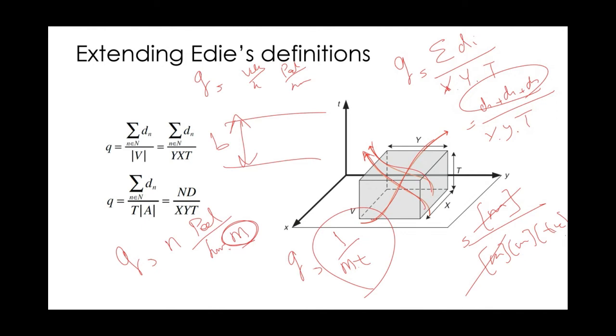So the wider the corridor that pedestrians are moving in, the larger the total flow would be, right? It's very similar to the number of lanes. Remember, in vehicular traffic measurement, we could say flow can be calculated as vehicles per hour per lane, depending on how many lanes it has. But because in pedestrian traffic we don't really have lanes, instead of the number of lanes, we have the width of the corridor that pedestrians are moving in.